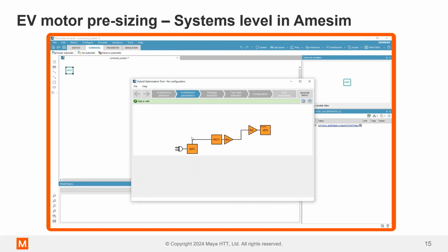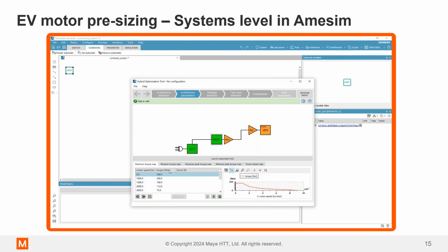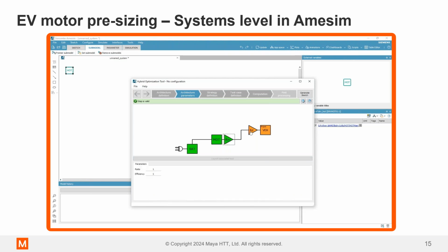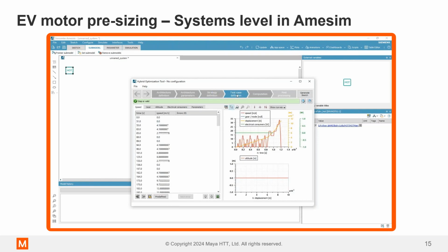This is a tool that lets us define the whole system level model. When we're talking about system level models, that'll be a big sketch, a big chart of all the different little components that are involved in our system, in this case, an electric car, and connections to define how each block and each component acts and how they interact with each other. So here we've been able to say that we're going to build a purely electric vehicle. We've got a battery and a motor, a vehicle, some control circuitry. We can define some motor behavior. We can define a drive cycle.